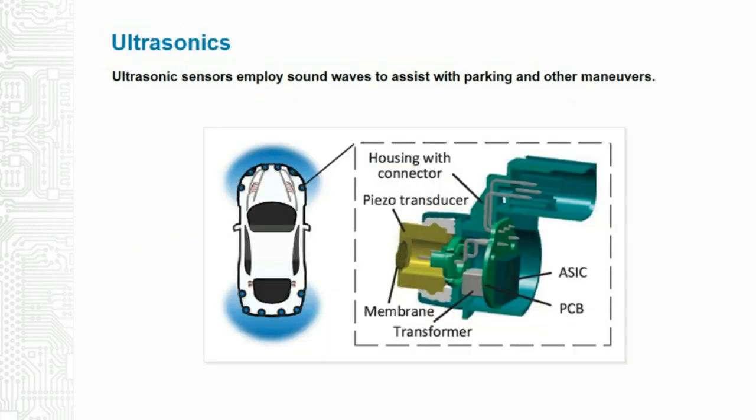Ultrasonics use reflected sound waves, not unlike what a bat does, to calculate the distance to an object. In the latest generation, I mentioned automatic and remote parking. In most cases, because of the short range involved, the parking system relies on ultrasonics. It supports emergency braking at low speeds by detecting objects that are close. It has relatively fast reaction to suddenly appearing obstacles.